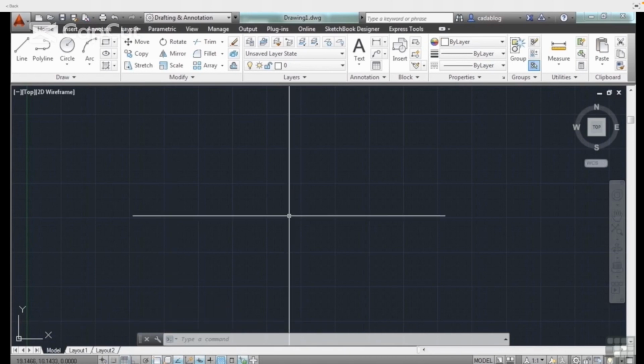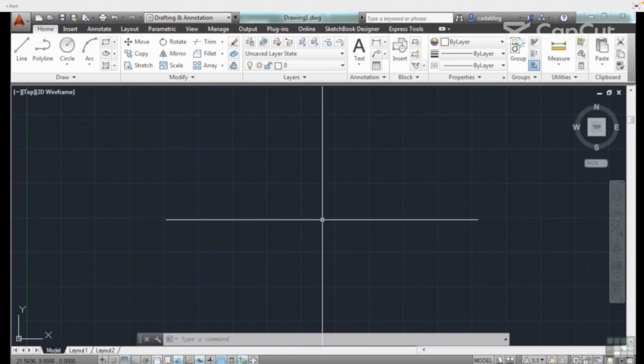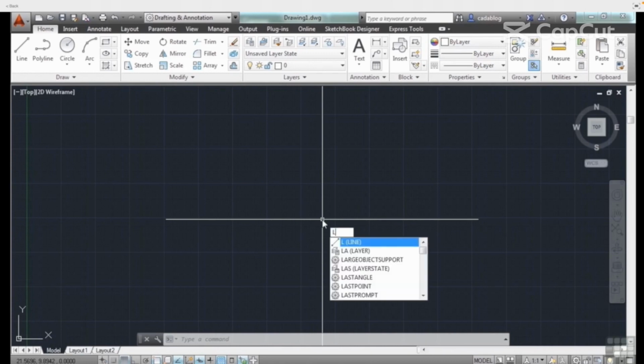Some people will even go so far as to get a 5-button mouse and program one of those extra buttons in the mouse to toggle the F3 button off and on, which turns the O-snaps on and off on the fly. There are times when they get in the way. There are times, though, when you absolutely have to have them. They make drawing so much easier. So pressing the F3 button will toggle them off and on. And once they're on, they'll be running. And when they're running, I mean like your refrigerator is running type of a thing. They're always on. So let's get a quick demonstration.